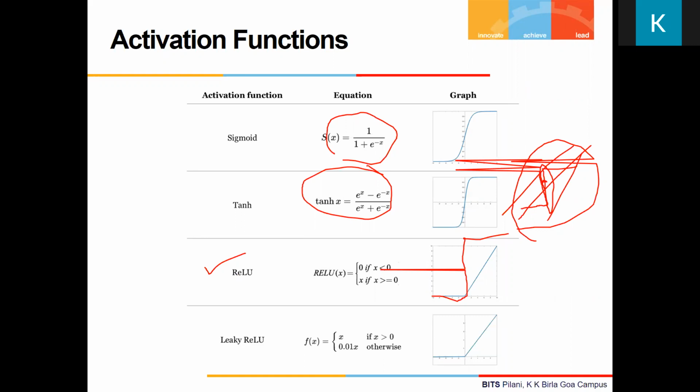And in case of FPGAs, we have IP cores, again CORDIC IP, which can find the exponential. Once you get the exponential, you have to do this one. Again, in case of division, you have to again use a CORDIC IP to do the division. So I'm not saying it is impossible, but the amount of hardware required for doing it is very high. And we need to keep the amount of hardware less so that I can implement more number of neurons in the given chip. So we will not go with exact implementation of this function.